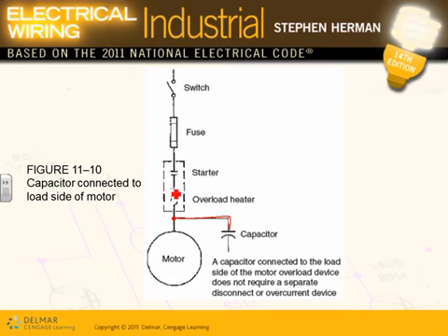then you have to adjust the overload here. You have to adjust the overload based on the corrected power factor. There is no disconnect and there is no overcurrent device. That's probably the preferred one. They go right on the starter and you add a capacitor. And this conductor cannot be less than 1/3 of the full load current of a motor. That's my capacitor, the conductor size.